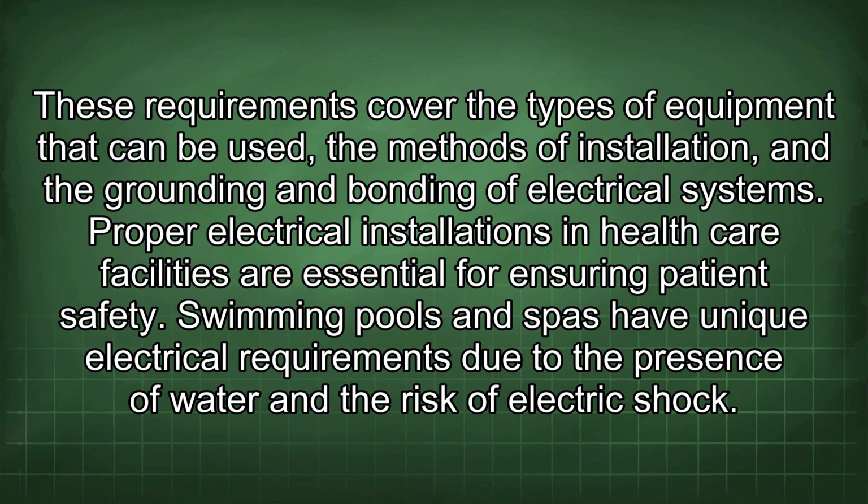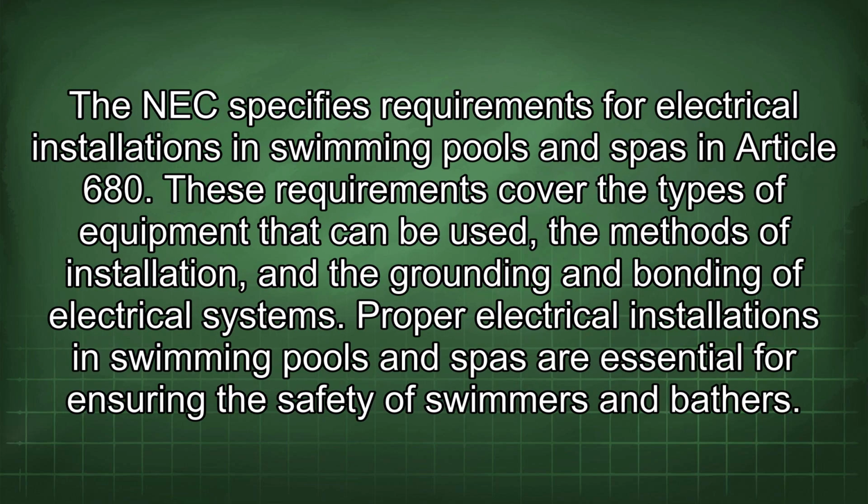Swimming pools and spas have unique electrical requirements due to the presence of water and the risk of electric shock. The NEC specifies requirements for electrical installations in swimming pools and spas in Article 680. These requirements cover the types of equipment that can be used, the methods of installation, and the grounding and bonding of electrical systems. Proper electrical installations in swimming pools and spas are essential for ensuring the safety of swimmers and bathers.